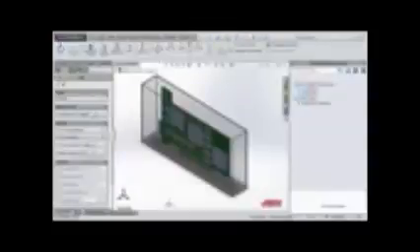Here, you can make changes to the modeling level of the board, compact or detailed. If you click on Layer Definition, a dialog box will appear where you can update layer thickness, percent cover, conductor, and dielectric material. We will select one of the components.